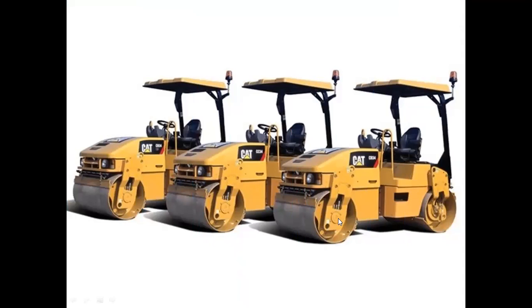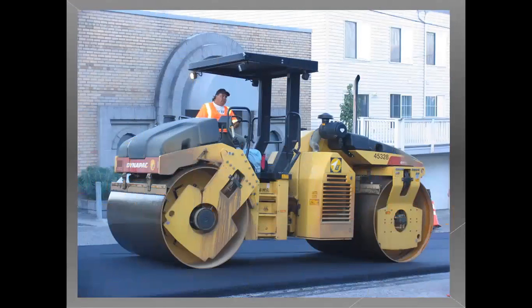Here you can observe this vehicle can weigh about 5 to 15 tons, so it is useful for gravel compaction or sand particle compaction. Soil compaction can also be done by using these smooth wheeled rollers. The roller can smoothly pass over the layer of soil or gravel, and the weight of its own vehicle helps remove any air voids between those particles of soil or granular particles. Here this is also a type of smooth wheeled roller.